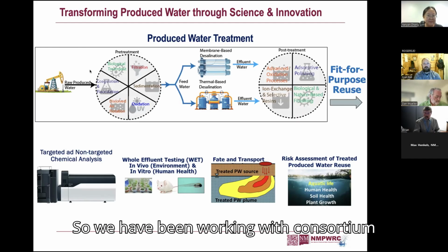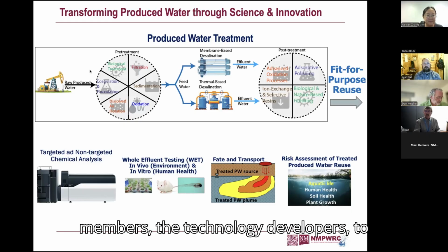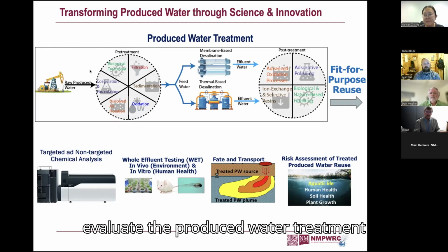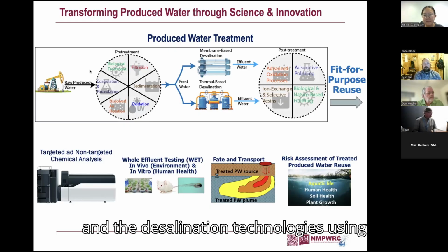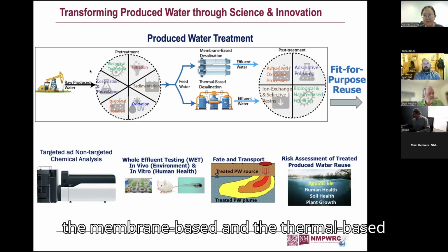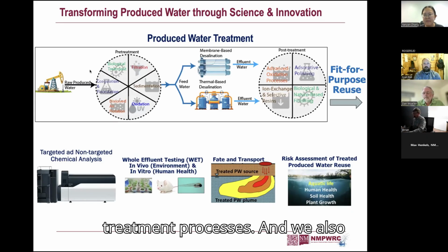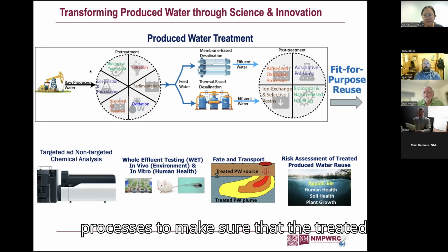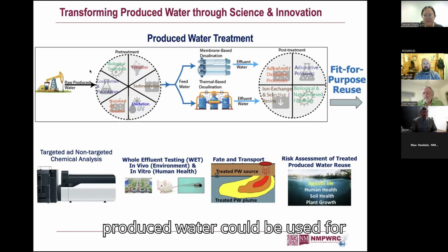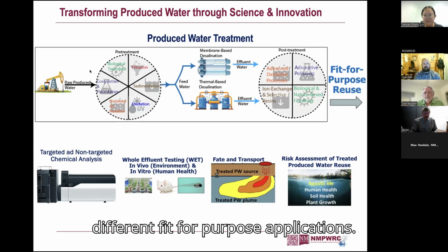So we have been working with consortium members, the technology developers, to evaluate the produced water treatment technologies through the pre-treatment and the desalination technologies using the membrane-based and the thermal-based treatment processes. And we also evaluated the different types of post-treatment processes to make sure that the treated produced water could be used for different fit-for-purpose applications.